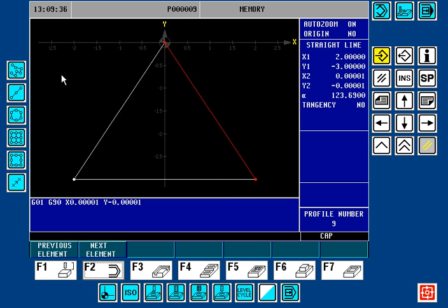When creating shapes in the profile editor for pocket cutting, they must all be completely closed, whether they're islands or pocket perimeters. They can't be open shapes like they can when profile cutting under the F3 key. When under the F5 key for pocket cutting, you must have all your shapes closed, which means that the beginning point and the ending points must be identical. Even being off 1/100,000th of an inch is enough to give you the error.